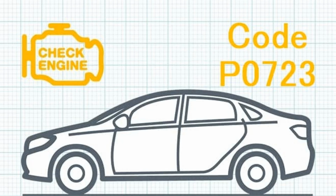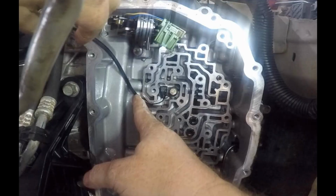Without an accurate output speed signal, the transmission control module, TCM, cannot change speed correctly, so this code is set. In electronically controlled transmissions, the output shaft speed sensor, OSS, is located at the end of the transmission in front of the drive shafts or drive axle. The output shaft speed read can be used to determine when to shift, as well as the torque converter timing and the electronic pressure control inside the transmission.